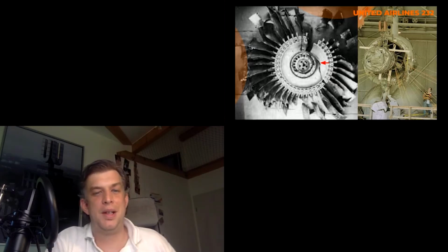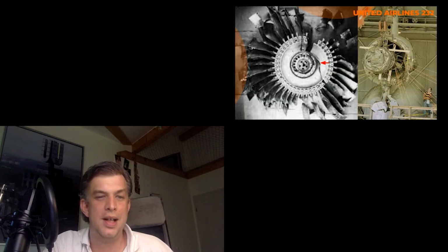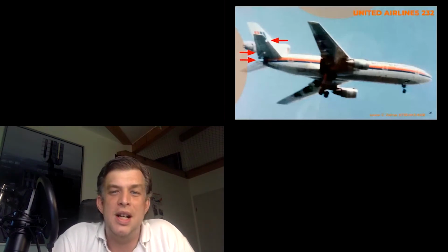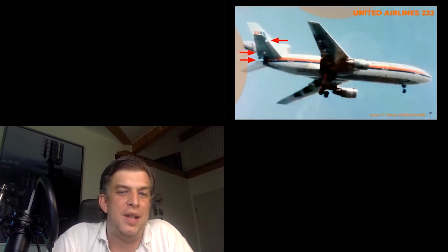The fan blade fragments severed the first and third systems' hydraulic lines. Parts of the first and second hydraulic systems were ripped off with the initial explosion. That forced a loss of all pressure and quick loss of all hydraulic fluid in all 3 systems. Within 2 minutes, all hydraulic fluid had completely drained from the lines. A photo taken a few seconds before the airplane crashed also shows the damage. The photo quality is not too good, but the light shining through big holes in the stabilizer speaks a very clear language.